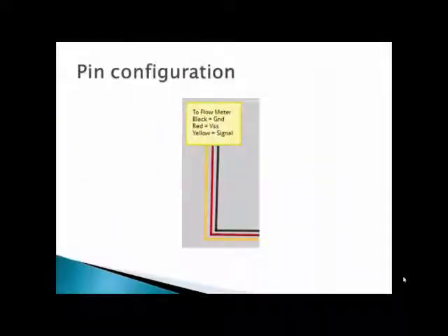The flow sensor. The first two wires are the normal standard convention, that's the ground and the voltage VCC. And the third pin receives digital input for each pulse generated as the water flows into it, and depending on the rate of the flow, the pulses generated are either fast or slow.